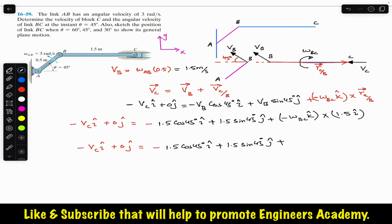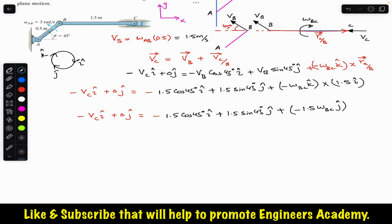So what is k cross i? Let me draw this circle. So this is i, j, and k. If we look into this, then k cross i will give us positive j. So we get minus 1.5 omega BC, and k cross i is j. So now we can compare both sides of the equation. We can equate i term with i and j with j.